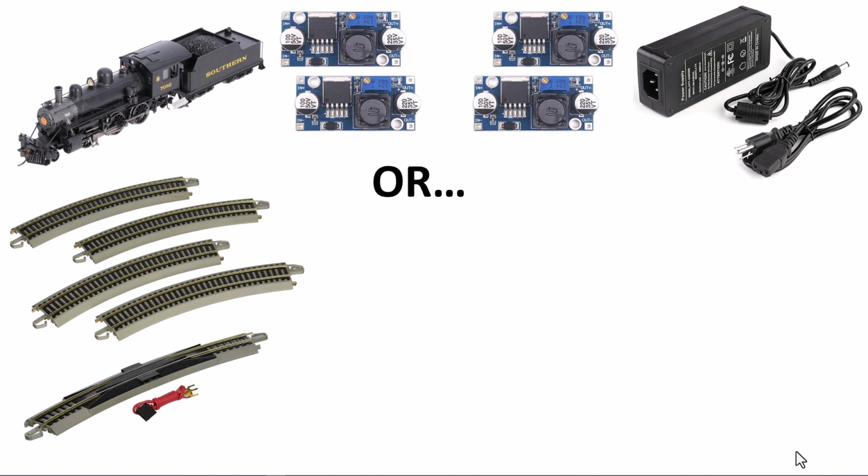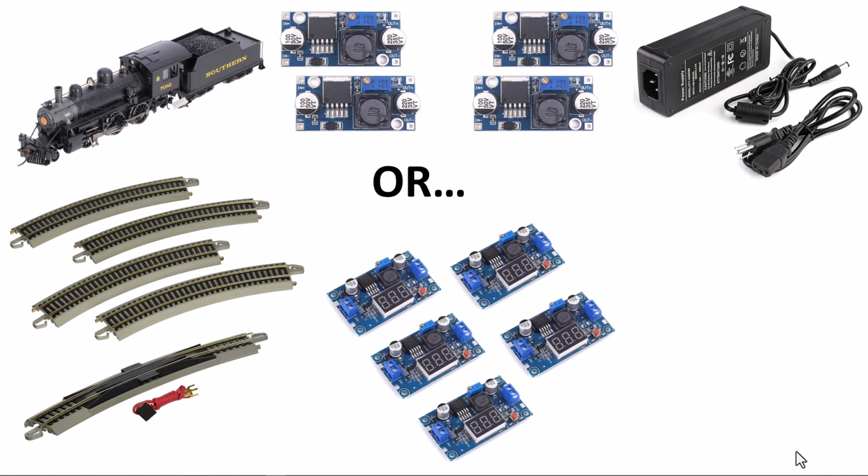And these circuits, you put in 24 volts DC, and then you could get out anywhere from 1.5 up to about 24 volts. So you can adjust the little brass screw there on that blue potentiometer to get the voltage you want. Or this is the route that I went.